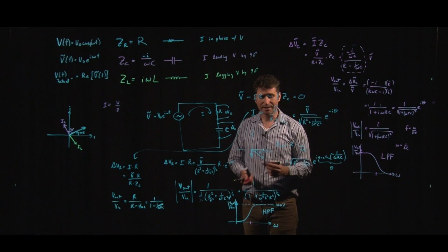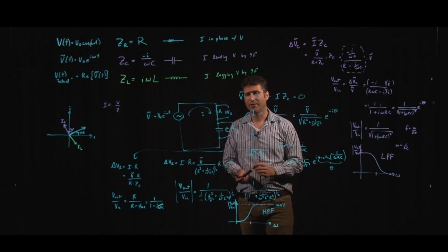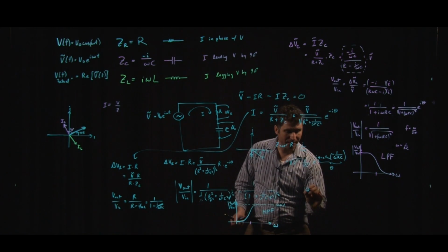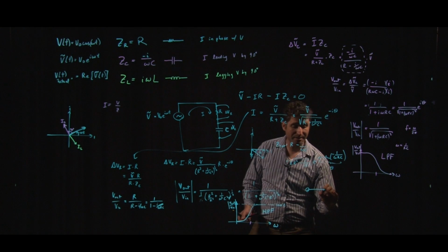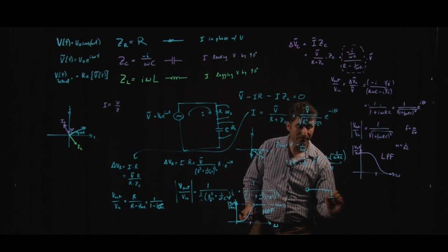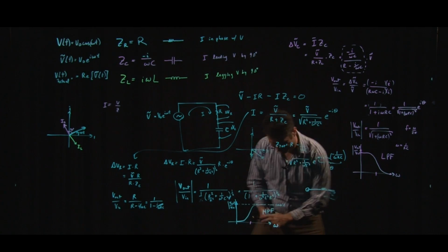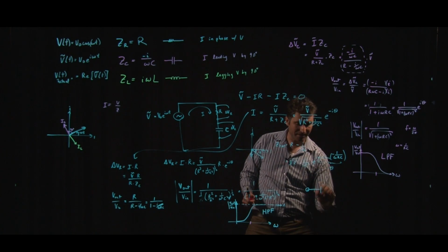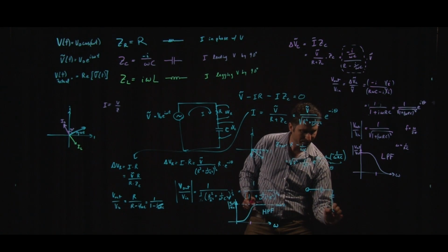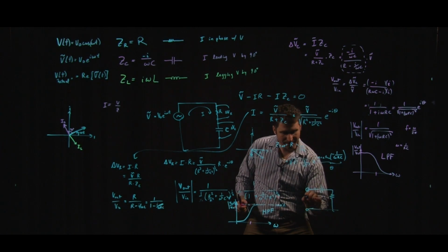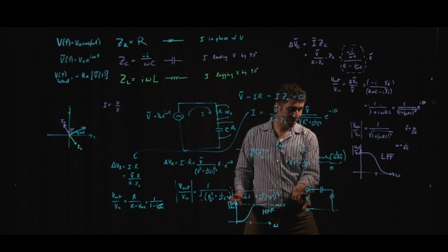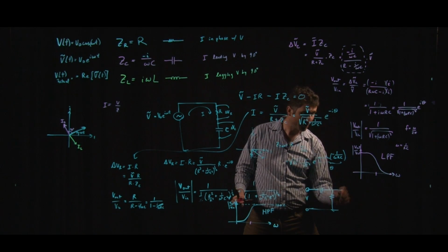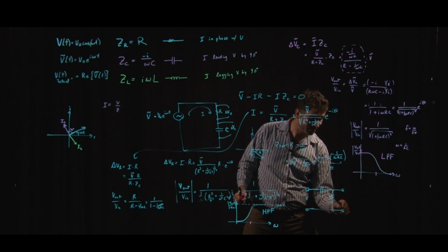So finally, in summary, I will draw now what is typically called a high-pass filter. The normal way of drawing this is that you have a resistive component, and then, oops, let me draw it appropriately here. So our high-pass filter, we're going to have a capacitor and then a resistor. And usually we're talking about a voltage that we're going to hook up across this capacitor and then going through this resistor to ground. And then we're going to measure the voltage drop across the resistor here.